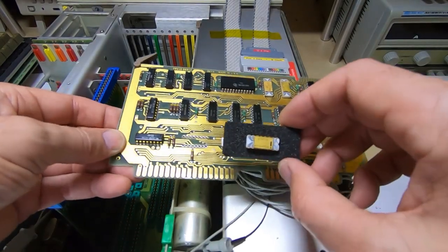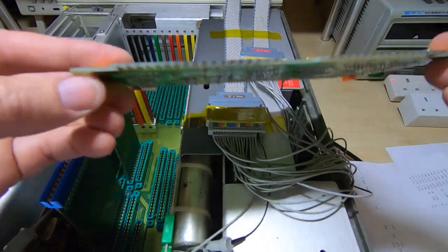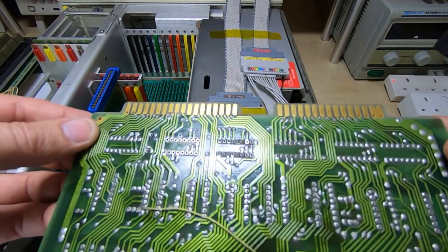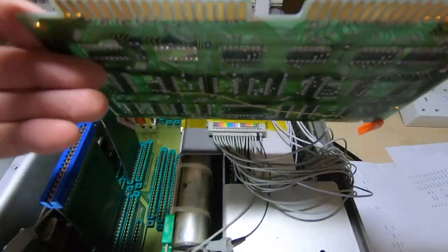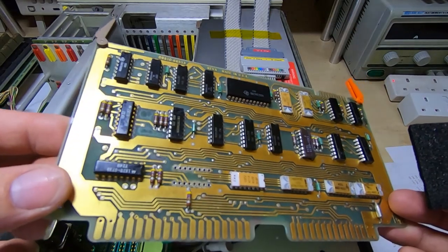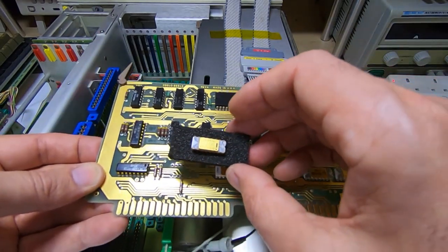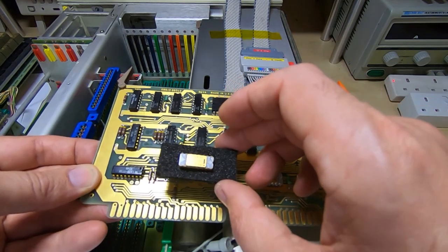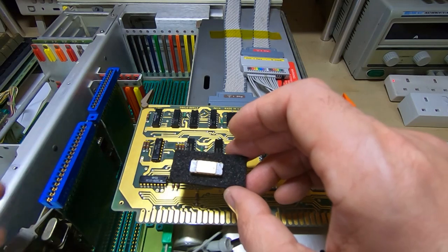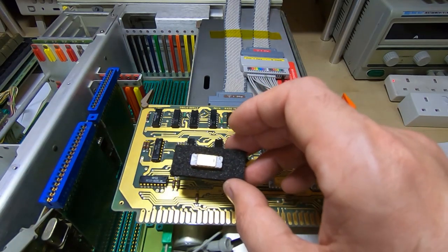Okay, so I've got the ROM chip out of the board. I've managed to do it without damaging either the chip or the board, although it's surprisingly difficult to get these ICs out of this particular board. The solder seems to have completely dried up and it just will not flow, so getting this out was quite tricky, but I've got it out. So what I'll do now is take it over to the programmer and try to read it and see if it really is dead, and go from there.